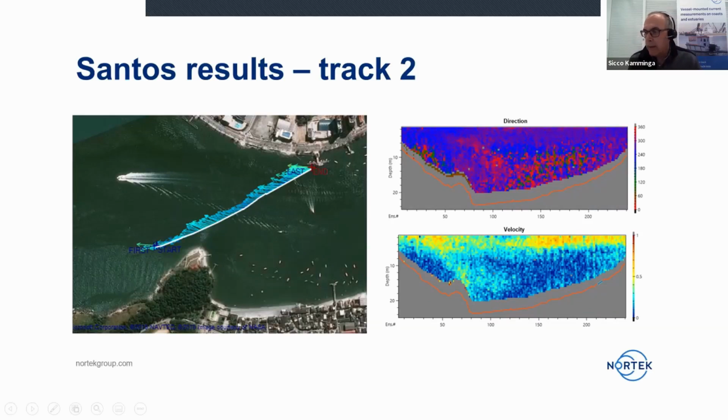So this was 6 hours later, a very different tidal regime. And there we have, again, our flow vectors, where you see at the end point they're pretty strong, much stronger than we observed before. This is the average flow over the whole vertical. So this area is pretty strong, and actually the direction also changes here at the start, and there's a little change in here.